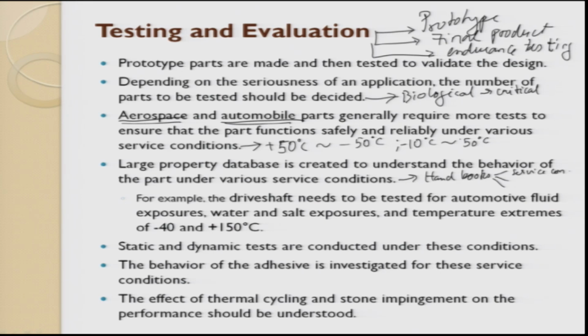We recently worked on a project wherein we were trying to make gaskets. Gaskets for two mating surfaces, and we made perfect castings at room temperature. But we did not realize that when it goes for a vacuum testing, these gaskets fail miserably. So at room temperature it worked perfectly. When it went for vacuum, that is a service condition, all these gaskets failed. So service condition is very important, and today you get handbooks which talk about that.